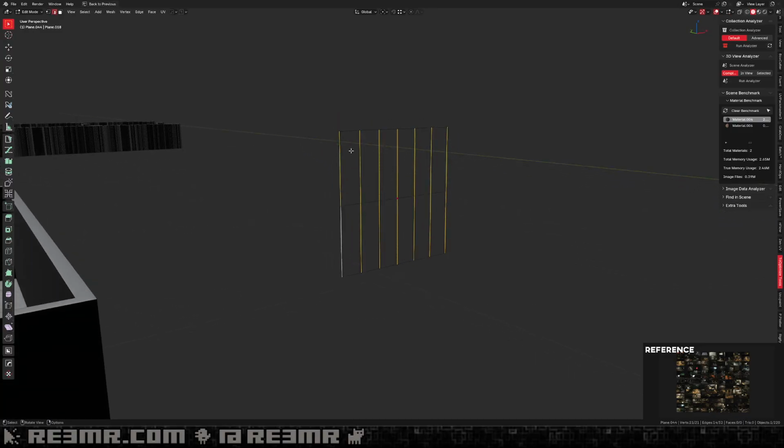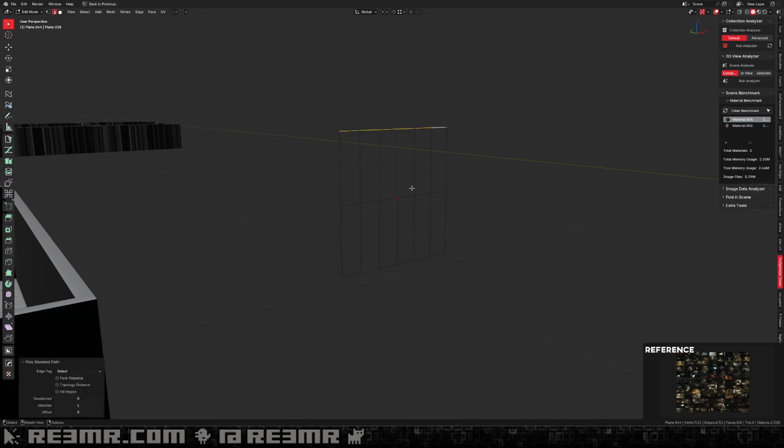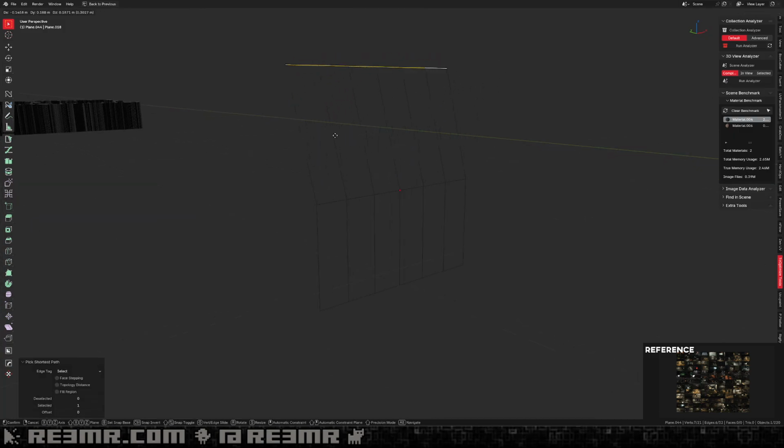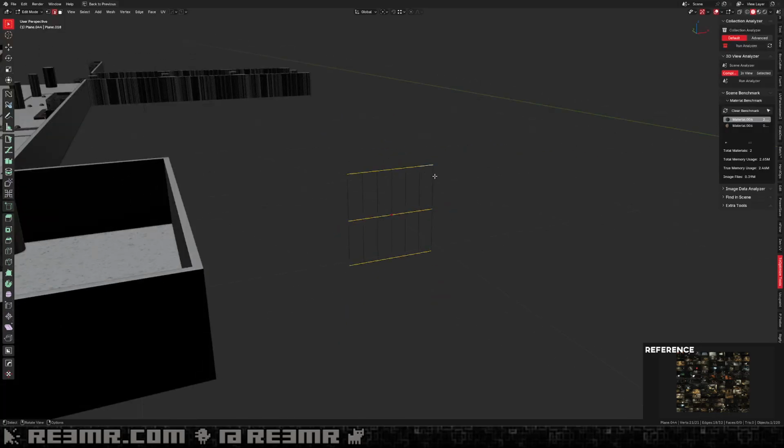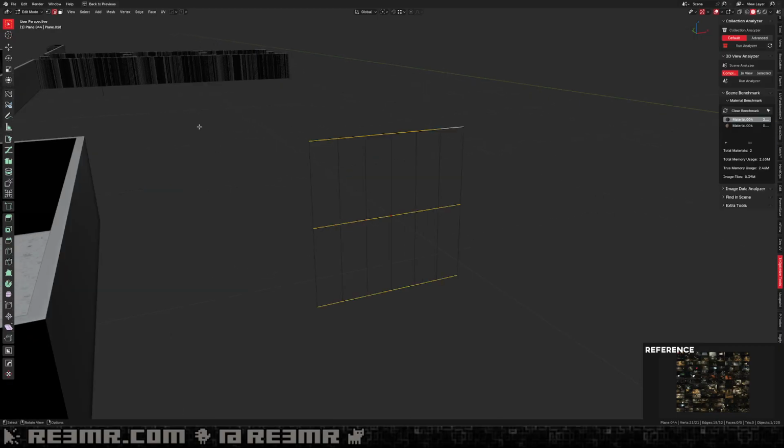So what I wanted to do was separate these, because right now these are all combined, right? They're attached. So I wanted to select similar direction and then press Y to separate these, right? And you see it dissolves these other edges. In previous versions of Blender, it didn't do that. So I noticed now instead I can go up here and split faces by edges, and that works.